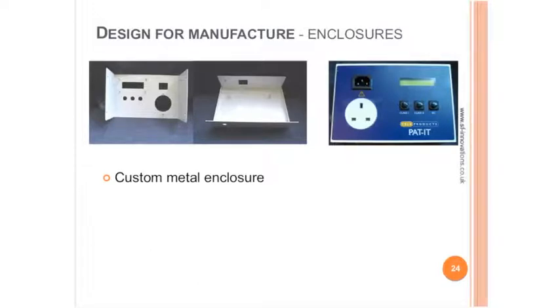So we didn't want to fork out on a tool. If you look at the pros and cons of this approach, it's very similar to the custom plastic approach. We chose metal here because we needed the strength. So low tooling cost. You might just need a die or two for the apertures that are stamped out in the metal here.